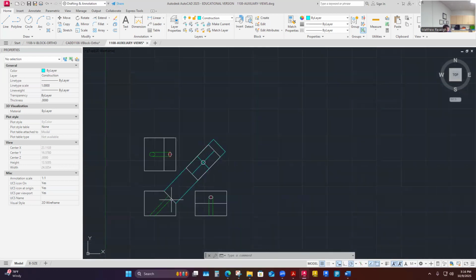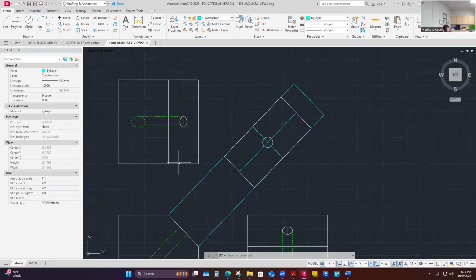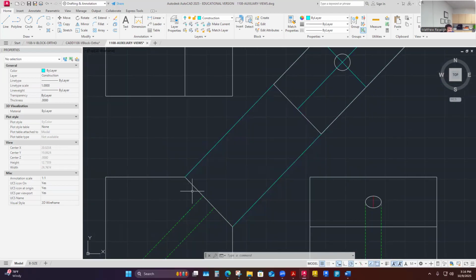I pick up that same surface on the top view with even a different dimension because now I'm in relation to what it looks like from the top view. And from there down, as it falls down and away from me, it's foreshortened. And it's actually the same length in the front view as it would be for the right side view or top, but the true length is found in the front view, and that's where I determine that's my projection plane edge to use. So I'm going to, and this V block doesn't break away from this orientation. It's the same orientation.